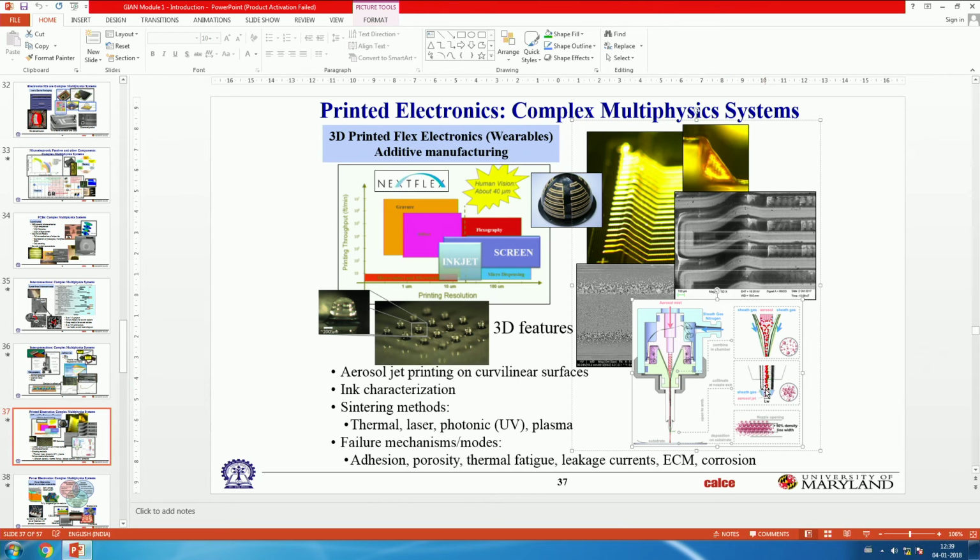Okay? All right. These were all, by the way, built by 3D printing. Remember, I talked about solder balls. Well, these are to replace solder balls. So you make polymer balls, and then you coat the polymer. Instead of having a full metal solder ball, you have a polymer ball, and you coat metal on top of that polymer. Now you have a conducting ball. So instead of a solder ball, you have this. So these polymer bumps are made by printing, and then the metal is printed on top of that.